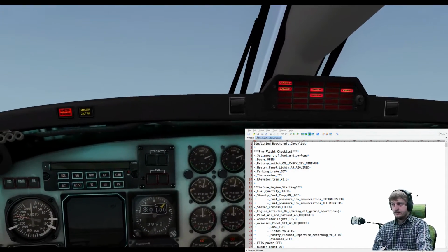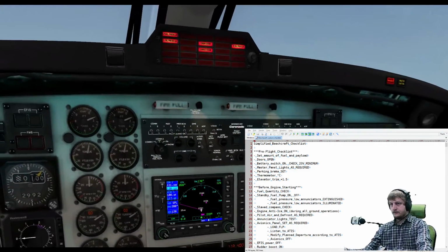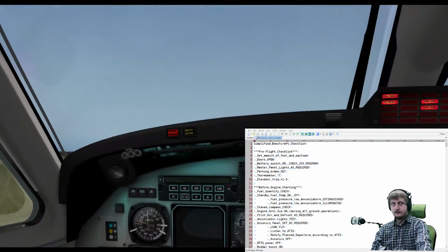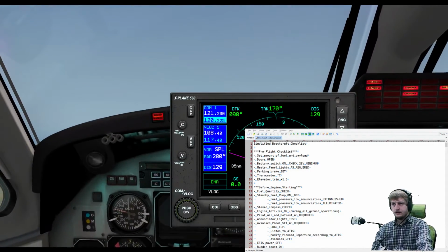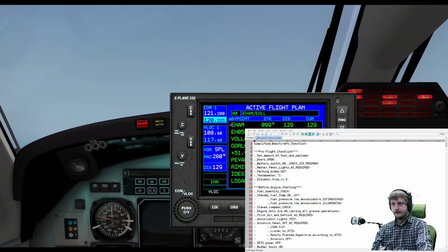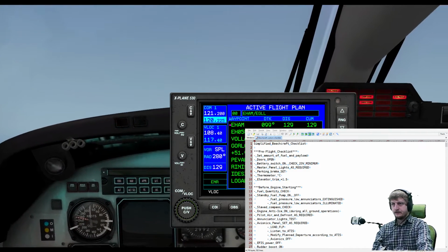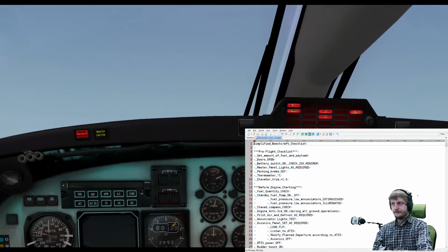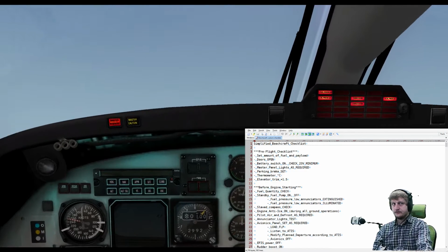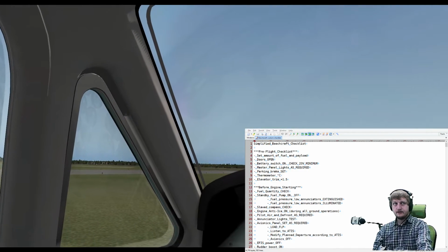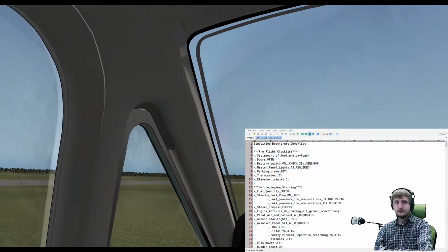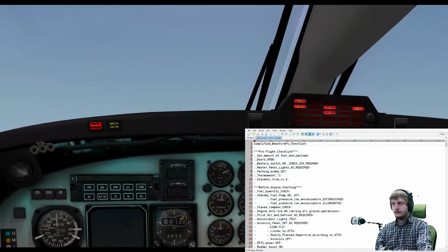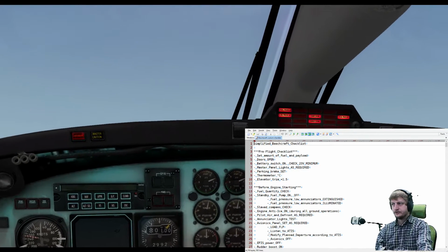Avionics 500 should be set as required, which means for us to load the flight plan. Let's assume this flight plan is loaded here. Okay. Load the flight plan. Listen to ATIS. Well, ATIS will be then done over the IVAO network. Modify plan departure according to ATIS.